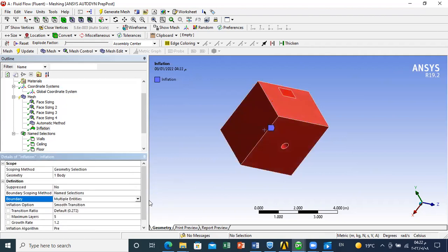Now you can determine the number of layers needed. So you will create layers near the surface. I will illustrate it for you in a sketch. In general, as I told you, the growth rate between the size of one layer and another should not be very large, because this will cause high variation in the size of the divided elements.